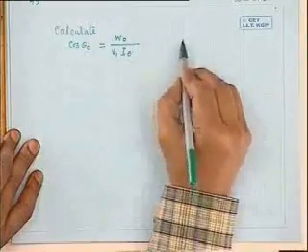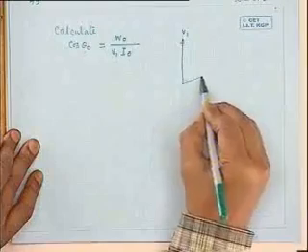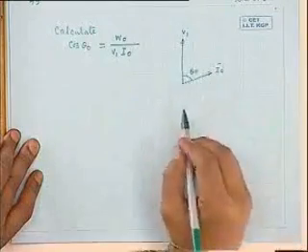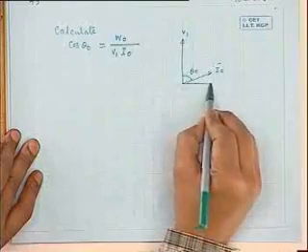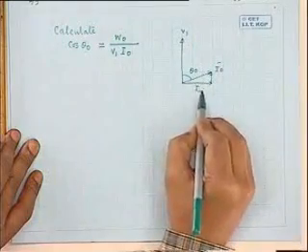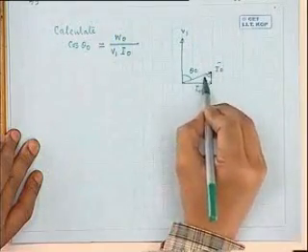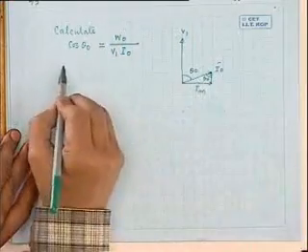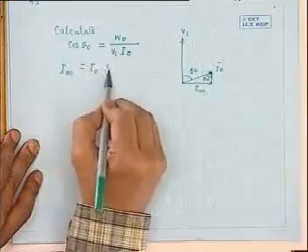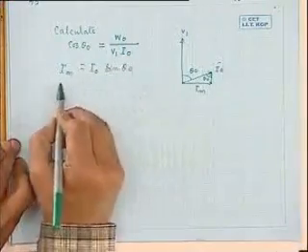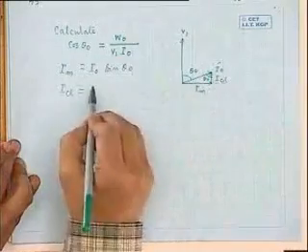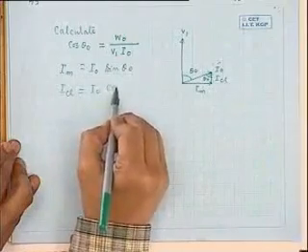So that this angle is calculated, from V1 and I naught. Theta naught is known. Then you can find out these two components, that is magnetizing component, by noting that this angle also will be theta naught. So then you calculate IM as I naught sin theta naught, and ICL, which is in phase with V1, as I naught cosine theta naught.